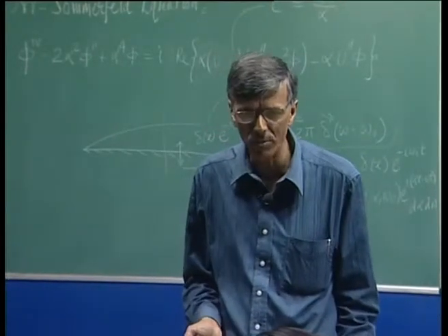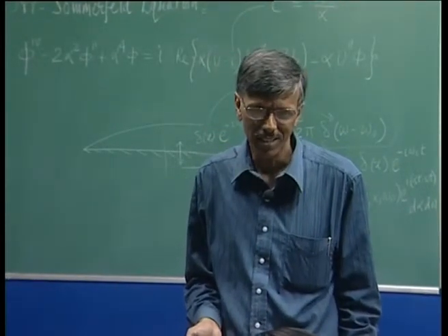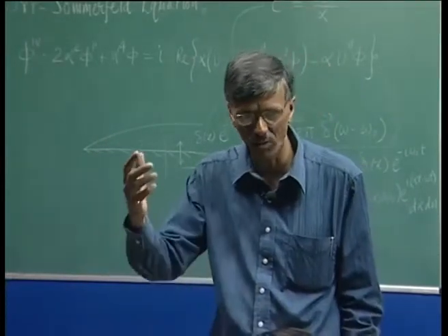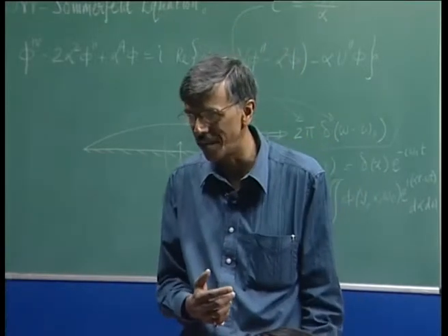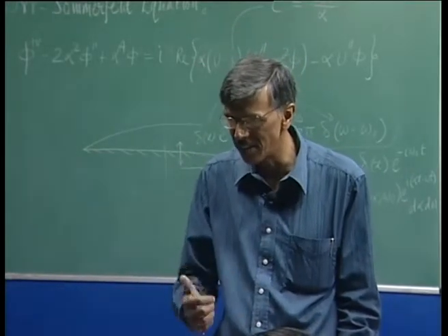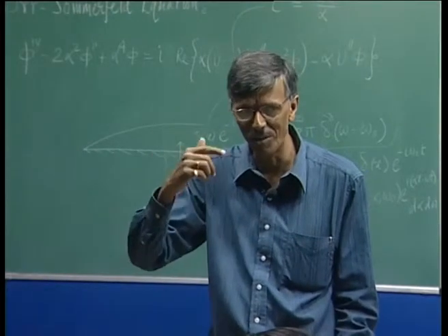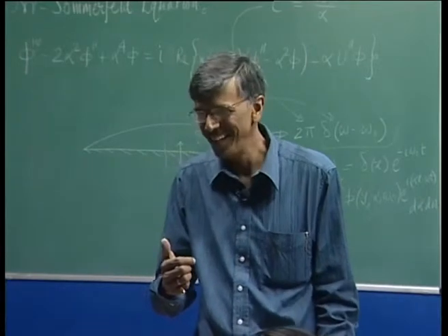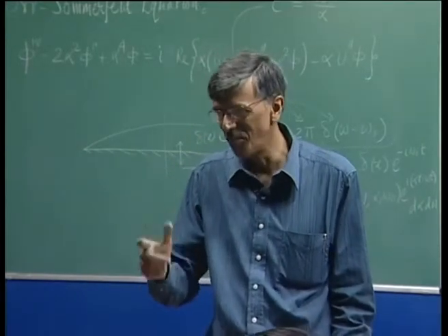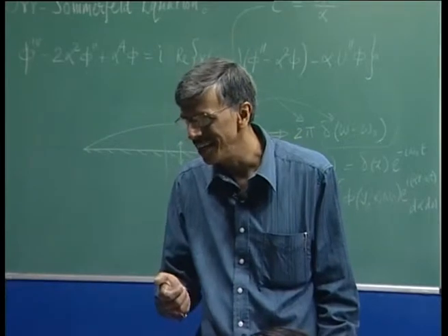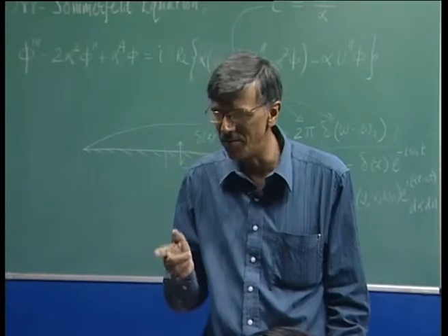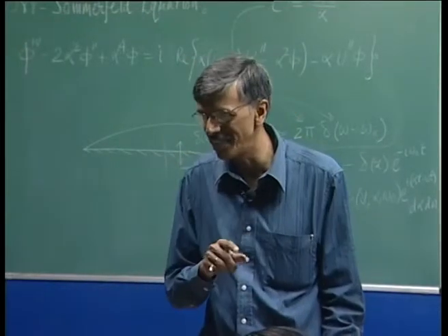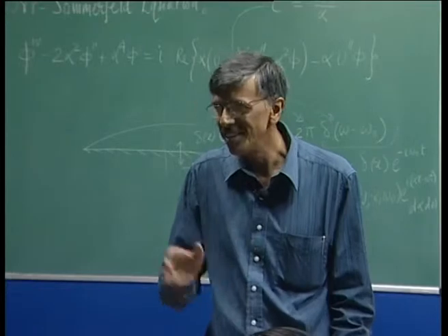We have figured out that if an atmospheric convected vortex is approaching the aircraft wing, then a pilot can decide whether to go over it or below it, provided he knows the sign of the vortex. If you are talking about a vortex which is rotating counterclockwise, it would be very advisable for the pilot to duck under it, and then instead of destabilizing the flow, it will stabilize the flow.